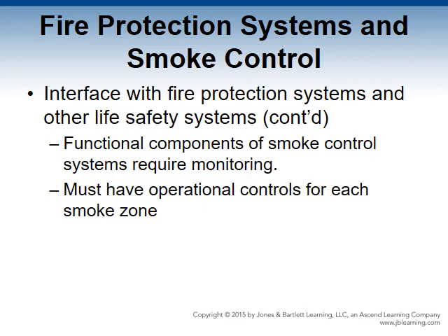Smoke detectors in elevator lobbies interface with elevator control systems to establish recall priorities during an emergency. In some jurisdictions, all smoke detectors and possibly all initiating devices interface with the elevator control to perform a recall. The most common recall method is to recall the elevator to the primary or alternative exit floor and to park the cab with the doors open. However, this does not result in significant loss of pressurization performance. Some elevators' doors have been adjusted to close after certain time intervals. Cabs are checked for people first.